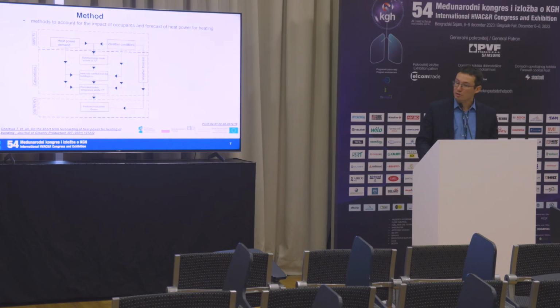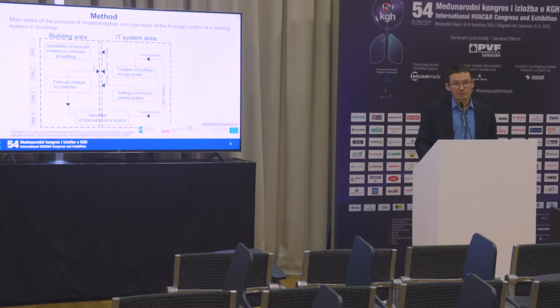That's why we also developed a method to easily take into account, without any sensor, profiles of equivalent indoor temperature. Based on this, we have two stages in our system. We have a building area where we have a module which makes our regulation possible, integrated with the existing weather-based control.